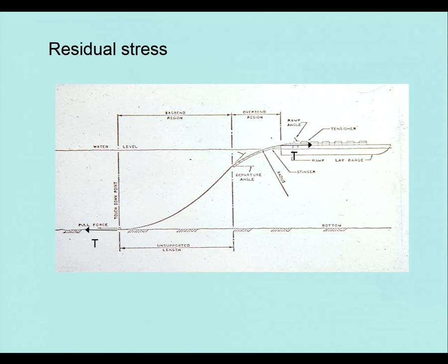Now all this residual tension is if I pull on that and the end of the pipe is stretching, and therefore it scrapes along the seabed, it stretches the seabed. And then when you take the force off, it shrinks back. But it doesn't shrink totally back. It leaves you with a certain percentage in there. And we normally say 10%. Okay.